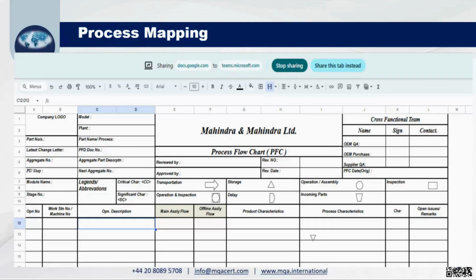There will be three parameters: what speed the machine should run, what feed rate I have to give the tool to cut the rod to make it diameter 10, and what depth of cut I have to give so that I will achieve the required specification. So this speed, feed, depth of cut is for the machining example.